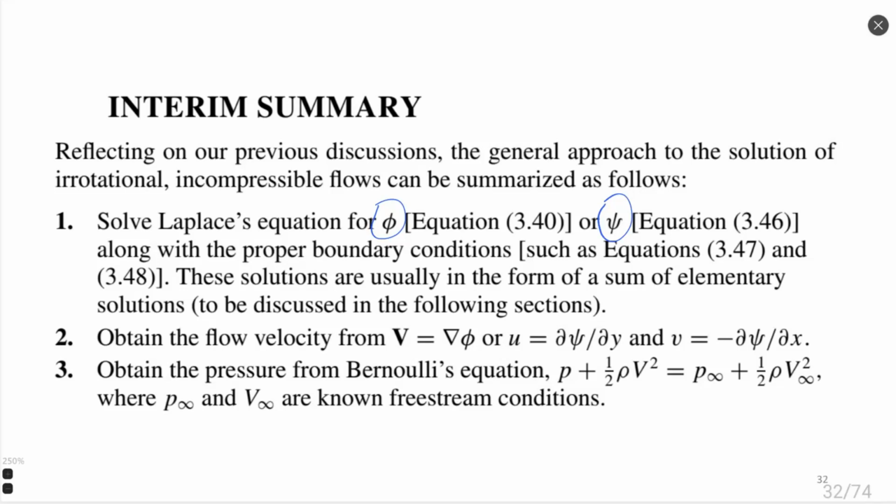And solutions of such Laplace equations form a sum of elementary solutions, or elementary flows, that we will discuss very soon. From the solution of the Laplace equation, we obtain the phi or psi function, and then we obtain velocity components just by taking a derivative of the streamline function: we obtain the u component of velocity, and with another derivative we obtain the v component of velocity. This is if we are solving in terms of